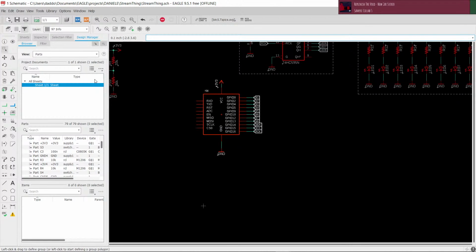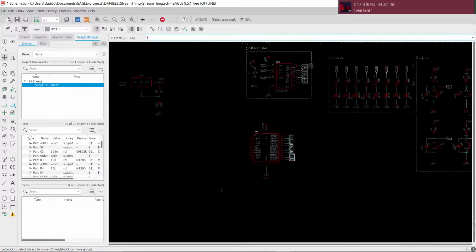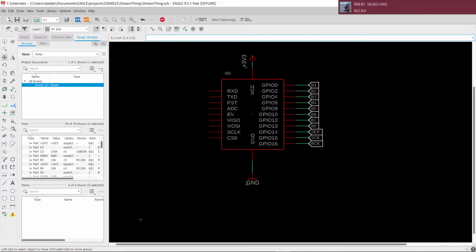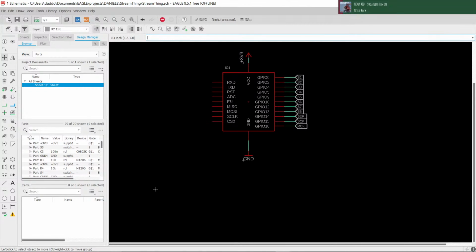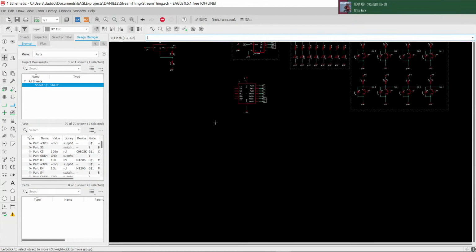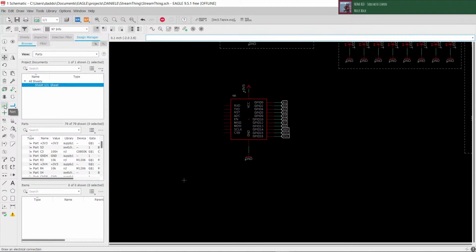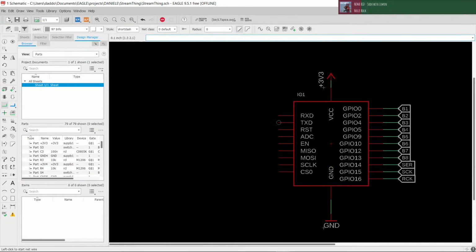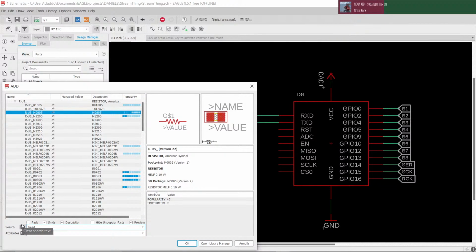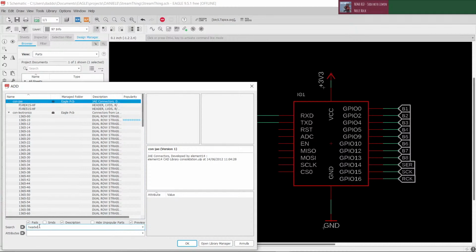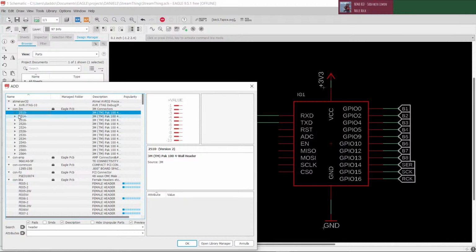Okay, this is the microcontroller, and I'm sure that there's a way to program the ESP12F over the Wi-Fi, but I also need to flash the thing before to be able to do that. So I will need breakout pins for RxD and TXD, remembering that this is a 3.3 volt part, headers. I don't want SMDs, I want pads.